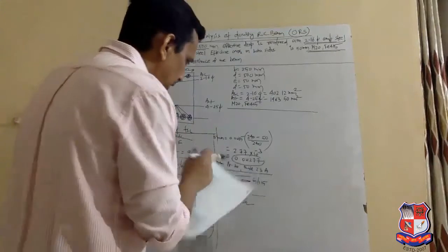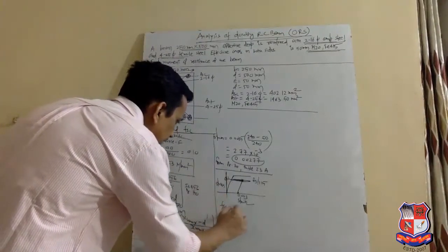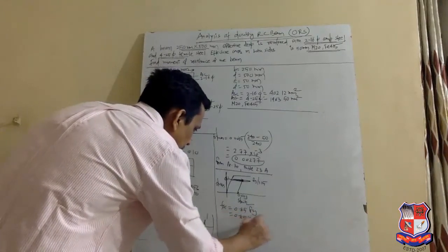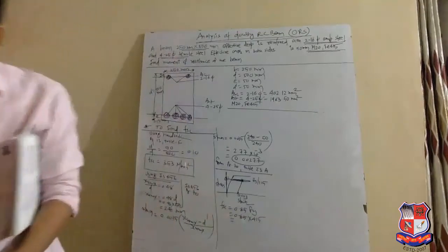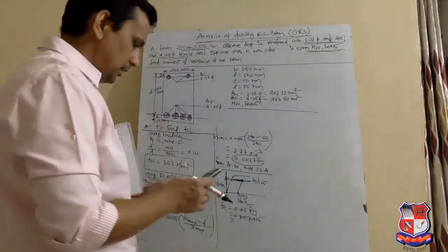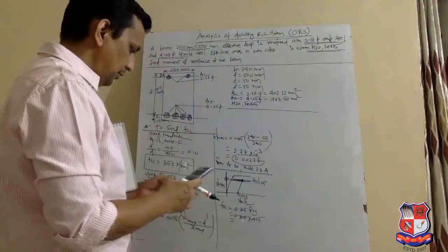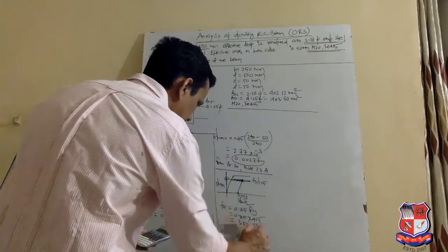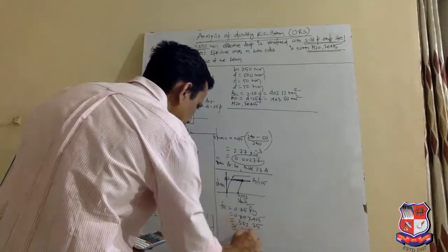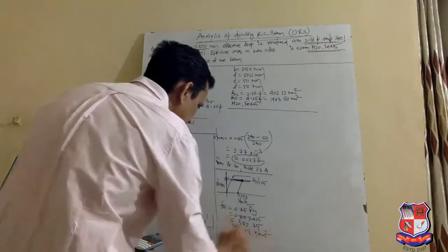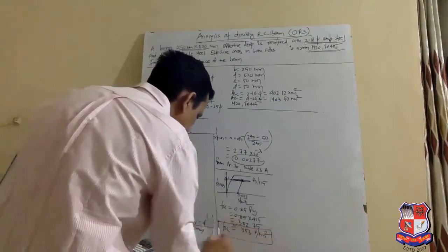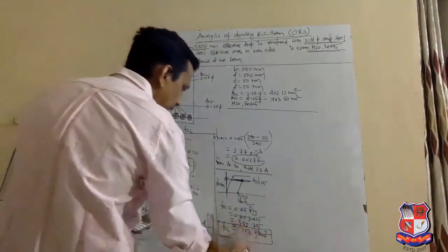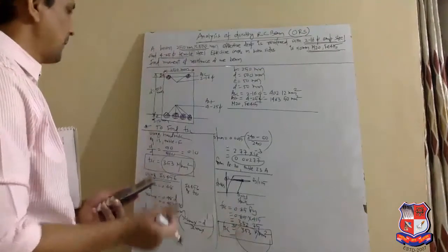So again, we get the FSC value 0.85 Fy, equal to 0.85 into 415. When we calculate this, we get 0.85 into 415, 352.75. It is almost 353 Newton per mm square. Right? The value from handbook as well as from IS 456 can be same.